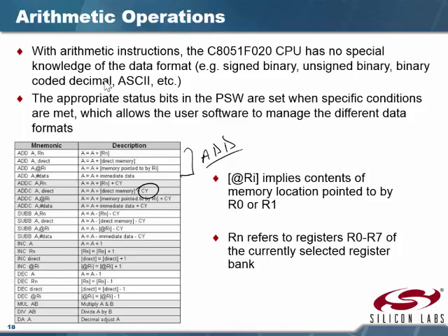All right, the next 4 instructions are just increments, followed by decrements. All they are is simply an add with a +1. And you can add to anything that you can address. So we can add to the accumulator, increment A. We can add to a register. Remember, we've got 32 registers set by our banks.